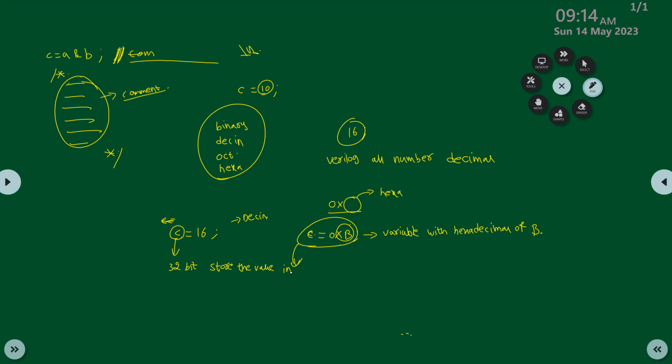And if you give multiple bits, let's say if you want to operate in such a way, you have to declare B with a port declaration like 3:0. Otherwise it is considered as only a single bit. If you are declaring B as input or output, that we will discuss later. If you declare input B, then it will be 1 bit, and this will be valid.